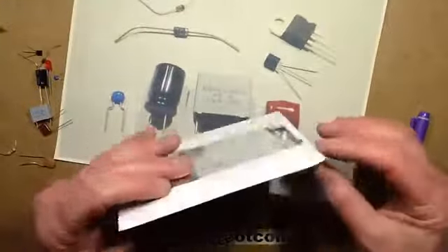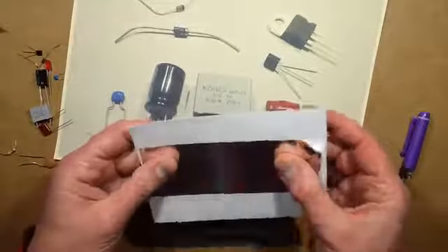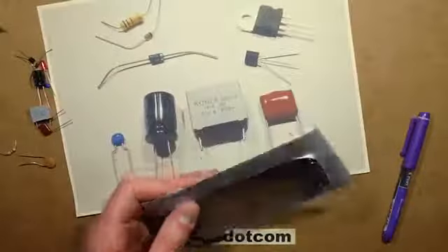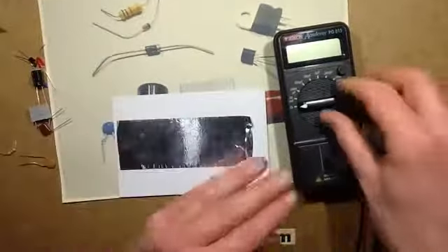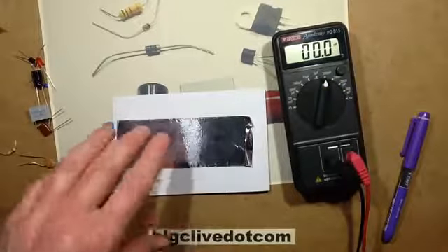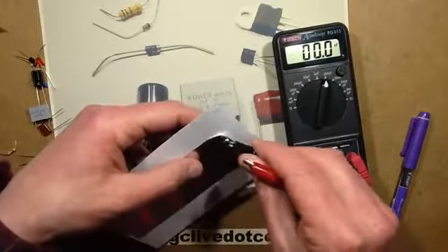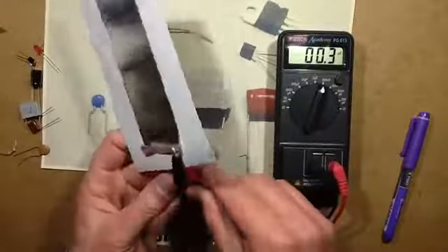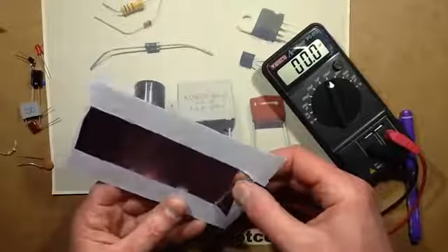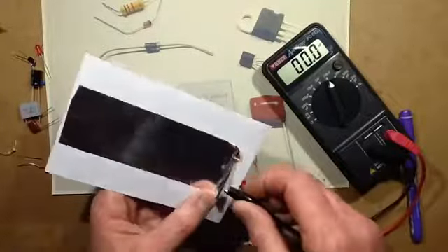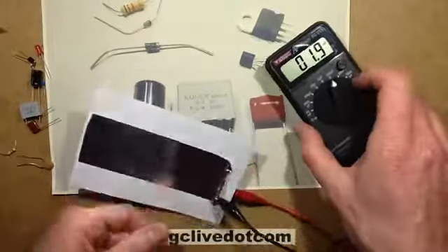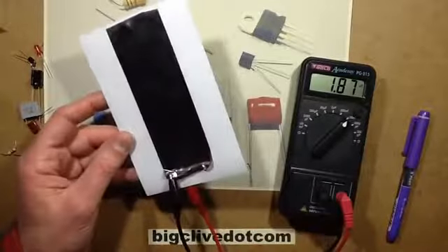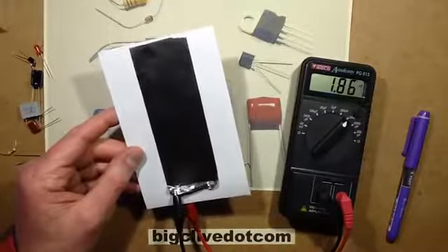And you'd think, you know, this card is very thin, so it's going to be a modestly high value of capacitance, but that's not true. This is not going to be a high value of capacitance at all. So let's be optimistic and say 200 nanofarad. And I'll connect it one side and the other side, and I'm actually connecting onto the adhesive side here. My capacitor measures... oh, that's terrible, isn't it? It's 1.8 nanofarad, it's not very high at all.